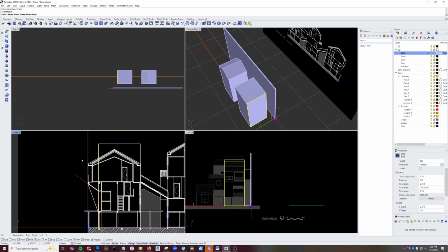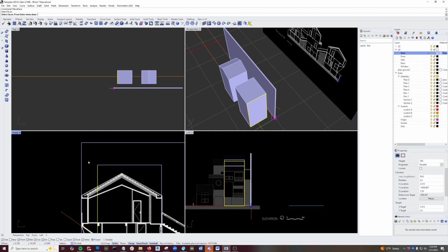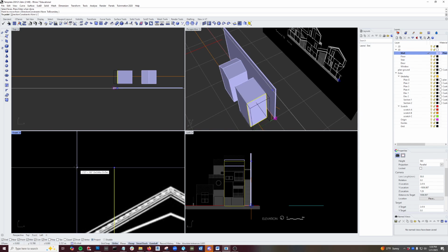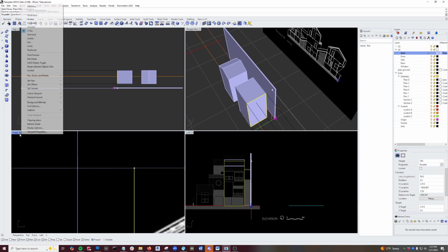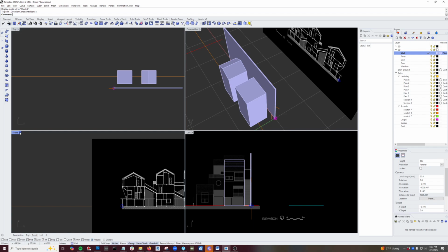And we could move that out, and it looks like it aligns with where this wall is. All right, so let's do that. Let's just align it. It's too shaded. So what's going on there? Let's set that to wireframe.